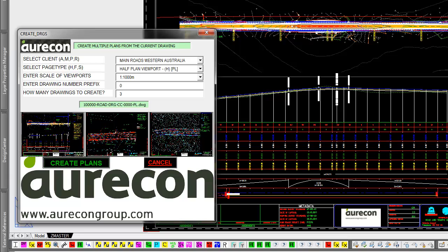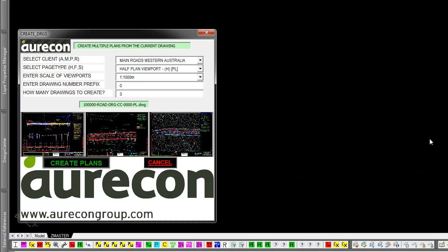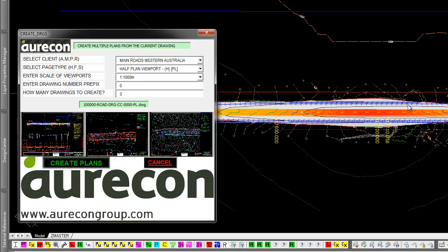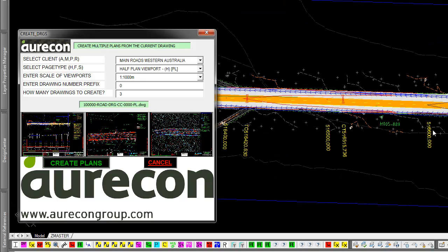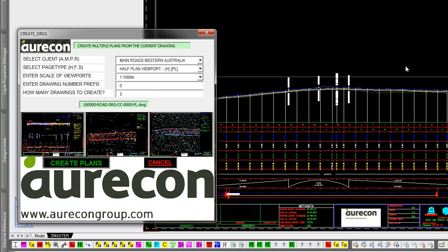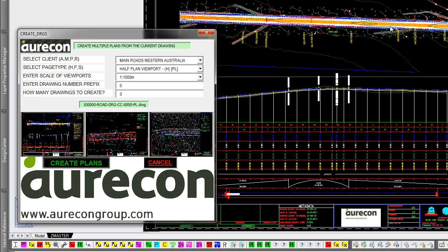file. It's masking off the appropriate layers for this file number, tiling over to model space. We're looking at UCS number 3 at the moment. That's the last thing it was looking at. It will be unclipped. It will restore number 1, set the UCS in the view for number 1, pop back into paper space and restore that information.